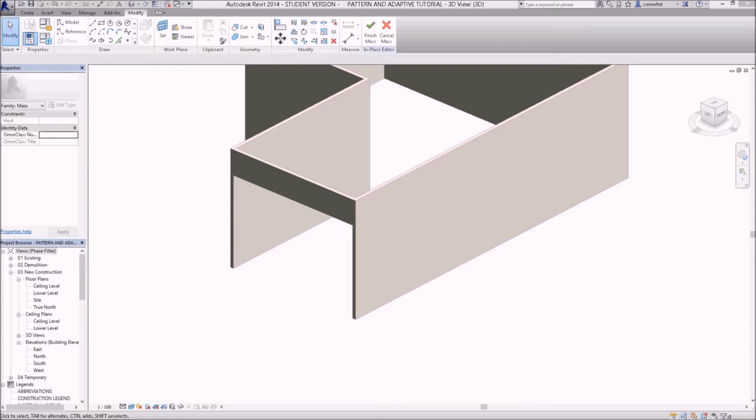I'm just thinning things up a little bit here. So frame 50 and brace 20. If I right click and go to its type properties, I can open that up and make the frame diameter 50 and the brace diameter 20, and click OK to that.